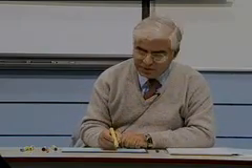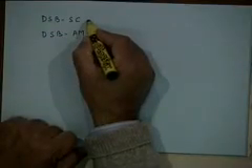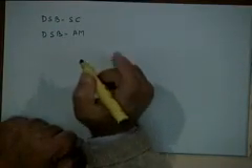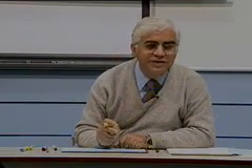So let me come back to the discussion regarding these two. One of the properties of the suppressed carrier DSBSC waveform, if you recollect, was actually not a nice property. We said that it is a disadvantage of DSBSC that if your local carrier is out of phase with the incoming carrier, you will tend to lose the signal, right?